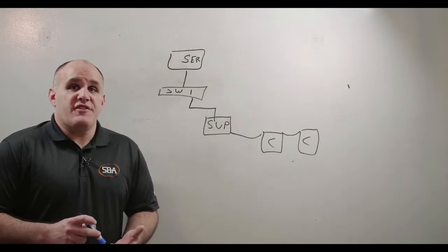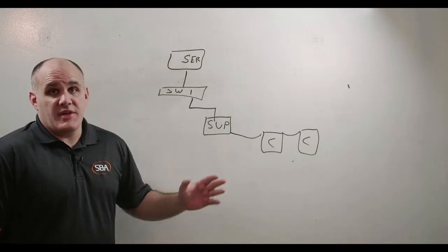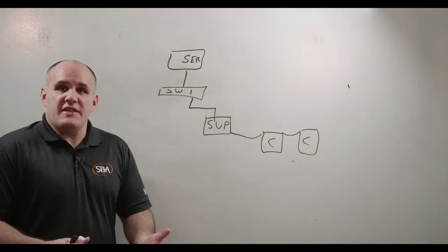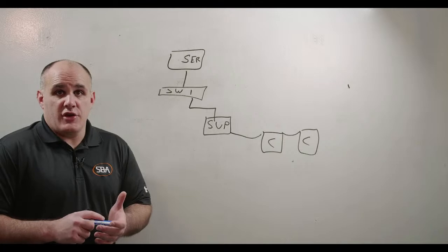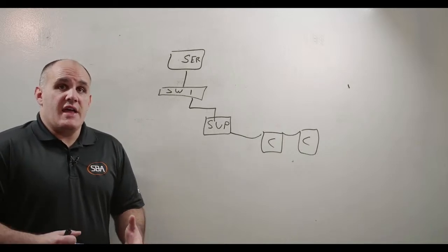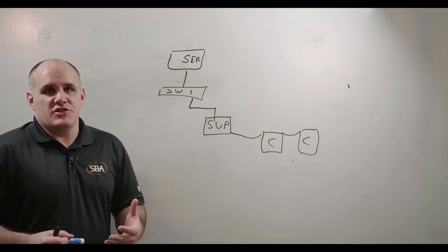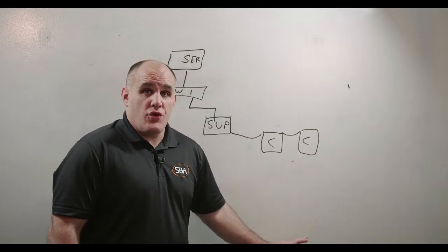So your primary focus here is going to be looking at those controllers, because those are often the most plentiful controllers within the building. If we're thinking of terminal units, fan coils, packaged rooftops, those are the most common and most quantity-wise controllers that we're going to find. So we'll go and address those application-specific controllers.